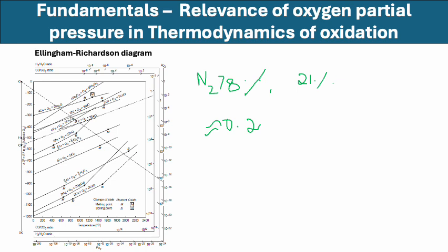If you want an equilibrium between metal and metal oxide, there is an equilibrium partial pressure that needs to exist, or else we cannot have oxide formation. So let's take the example of iron here, which was demonstrated already. Let's draw a line to mark what I'm talking about. This is the iron to iron oxide Fe2O3 line.